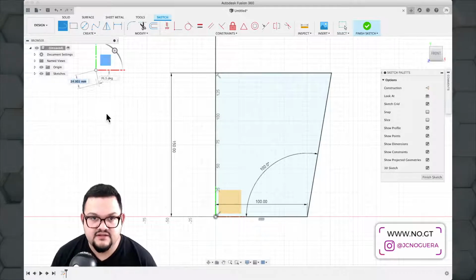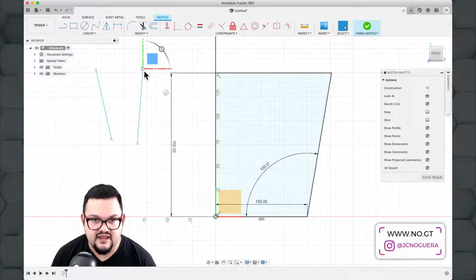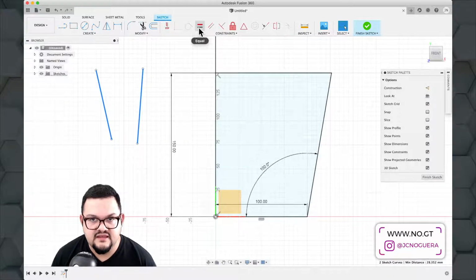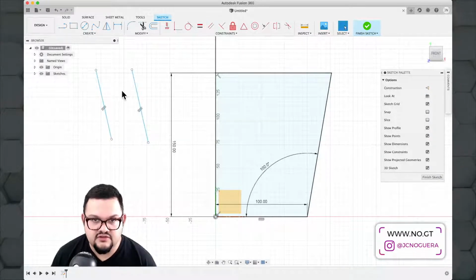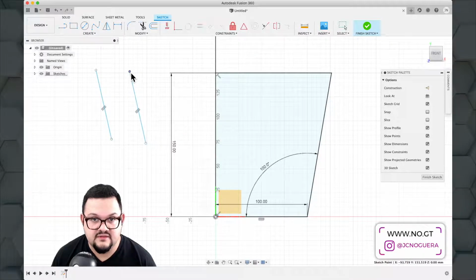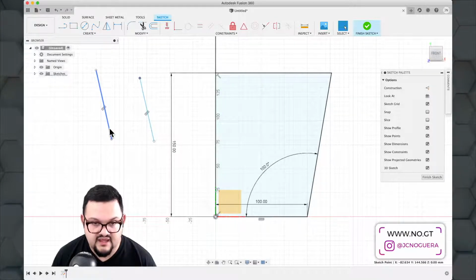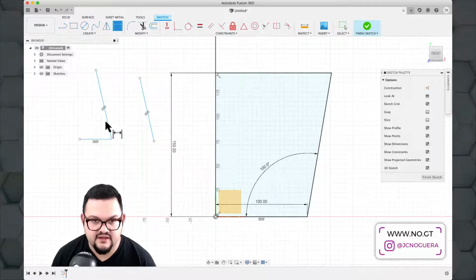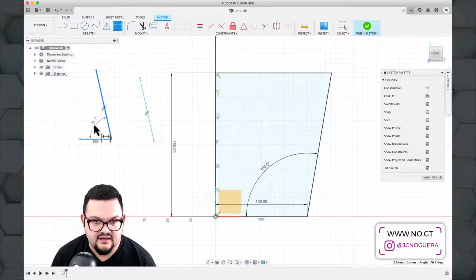Let's say you have 2 lines here, and they're going at different angles. These two lines, you can select these and you can say these are actually parallel. So whatever you do to modify one of these lines, it'll modify the other line as well. So these are always going to be at the same angle. So if we now create some kind of reference between these two, let's see if we can add an angle here.